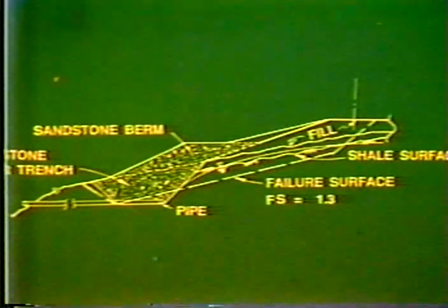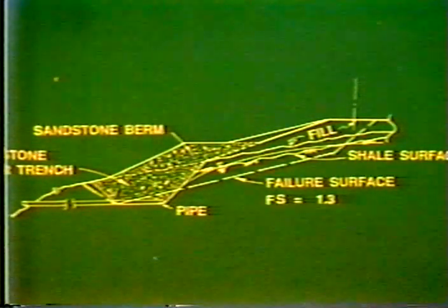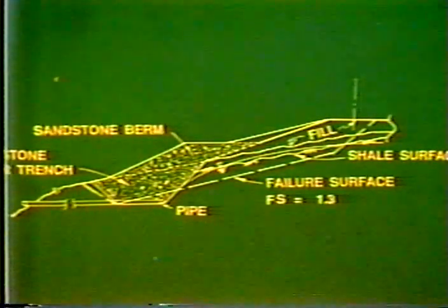And if you'll note the failure surface there, what we're trying to do is force it through that trench, through the high-strength material. And if we put it into rock, that's the only way it's going to fail. It has to go through that trench. But we've got strong material in there, so we've increased the safety factor.